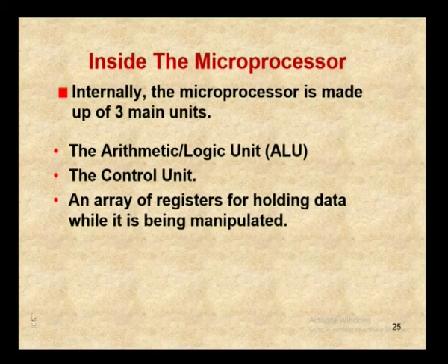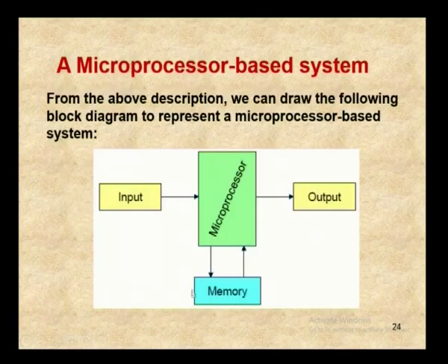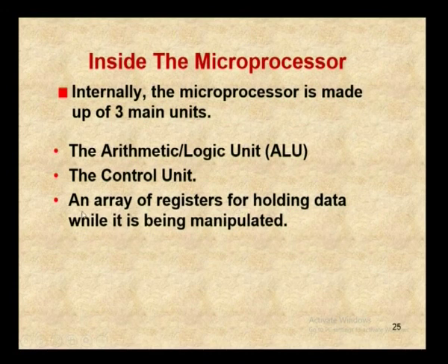In the previous slide we saw the memory. We have a memory here, but the microprocessor also has a few locations, maybe less than 10. That memory is called registers. The memory inside the microprocessor is called registers. They hold the data that has to be manipulated. It cannot be coming from the main memory every time, as that will take a lot of time. Therefore, the microprocessor generally manipulates 2 data at a time. So, add means it will add 2 numbers.